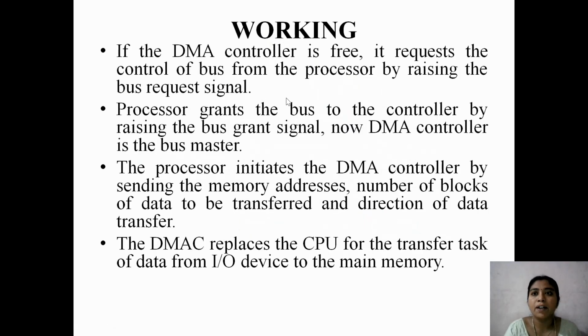If the DMA controller is free, it requests the control of the bus from the processor by raising the bus request signal. The processor grants the bus to the controller by raising the bus grant signal. Now the DMA controller is the bus master.